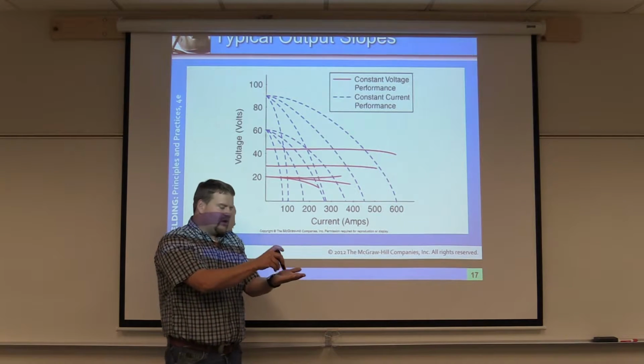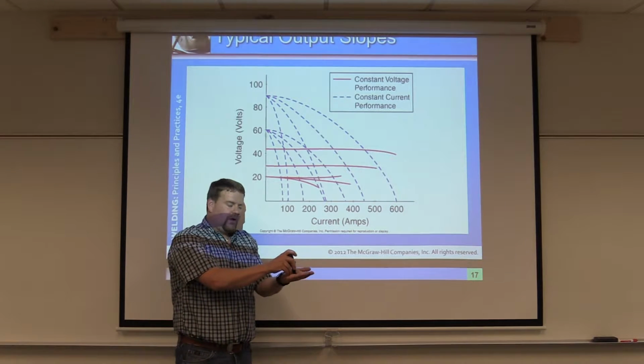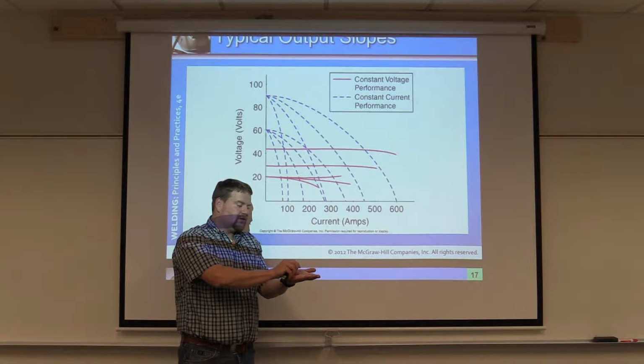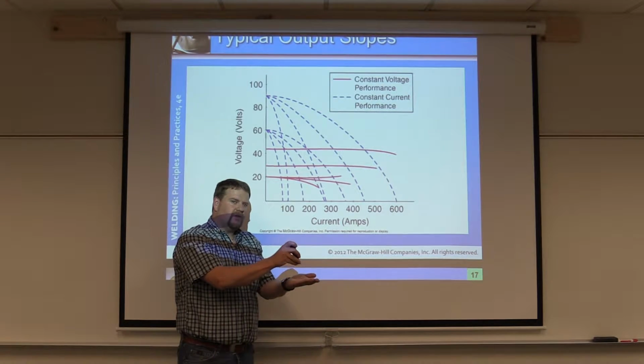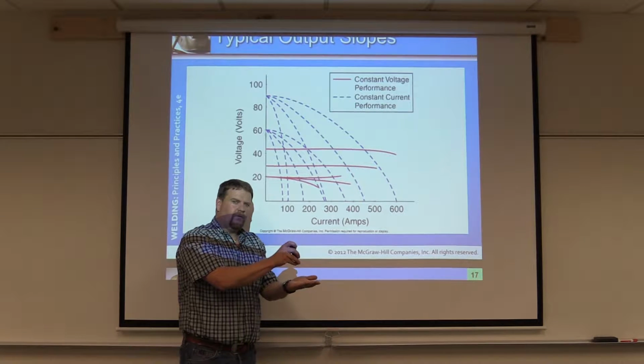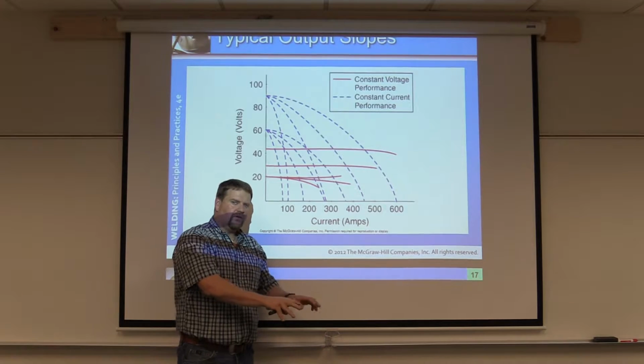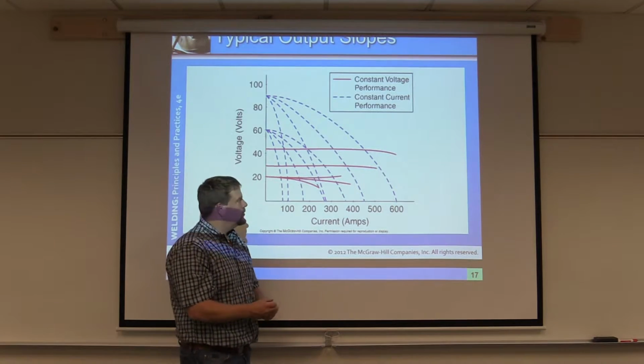If you're at 100 amps, it's trying to maintain 100 amps here. If you take it out further and create what we call long arc, so you're bringing your arc distance really far, then you're going to drive those amps up to say 120, 130, 140, and it's really trying to make that electrical jump to find the ground or the workpiece. Okay?